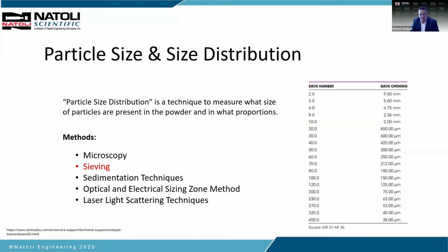And there are different methods for measuring your particle size and distribution. I'm going to be using the sieving technique, but laser light scattering is very popular as well. So I'm going to show you how we use the sieve technique. And on the right, I've given you the sieve numbers that you might see on your sieve screen and what the sieve openings are, in microns.